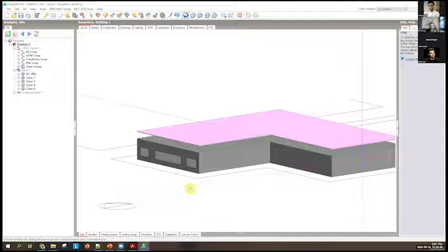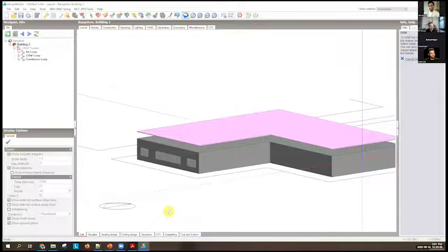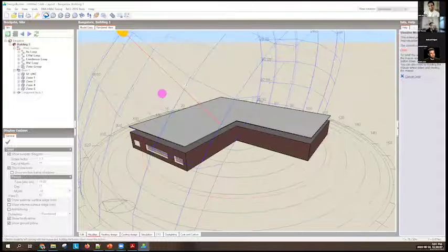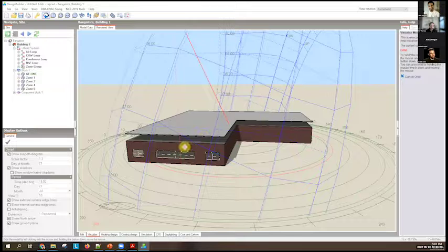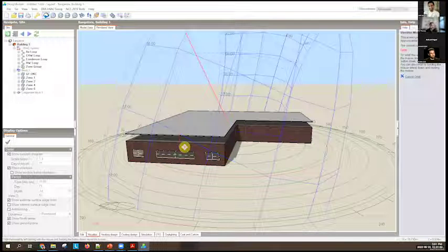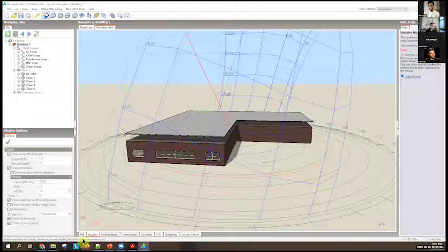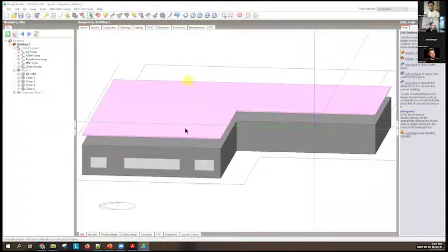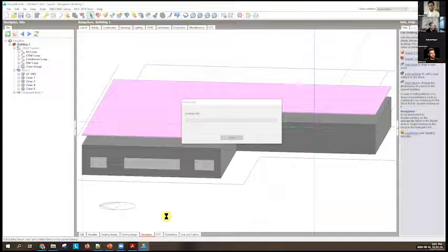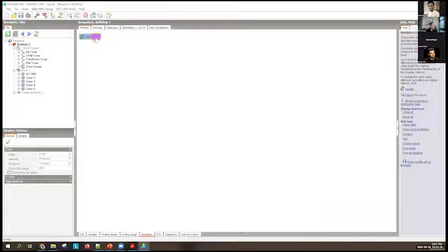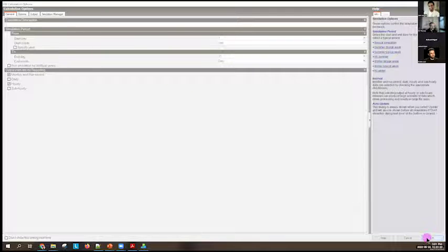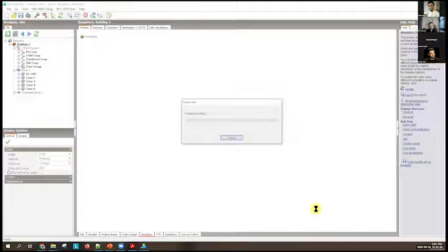The roof is the one that gives the highest cooling load. So all I've done is created a big shading device. You can see here that the roof is mainly shaded. Now, I expect that if I do this, my cooling load should come down. So if I do a second run, then if I look at the cooling energy use, hopefully that's come down a bit.